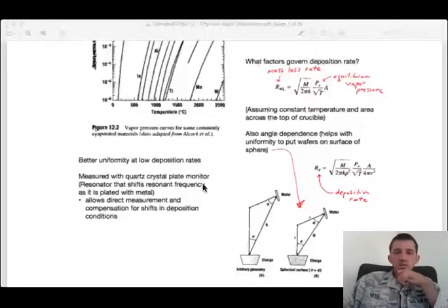So heating and rotating can help, and actually what you have in a lot of these cases with these evaporator systems is an arrangement like this that's kind of spherical, but it also rotates around continuously during the deposition, right? So you kind of have this planetary motion that helps to increase the uniformity and increase the step coverage. Right, and we know about diffusion, so we have this similar form here that if I increase the temperature, right, I have better diffusion of those atoms around the surface.